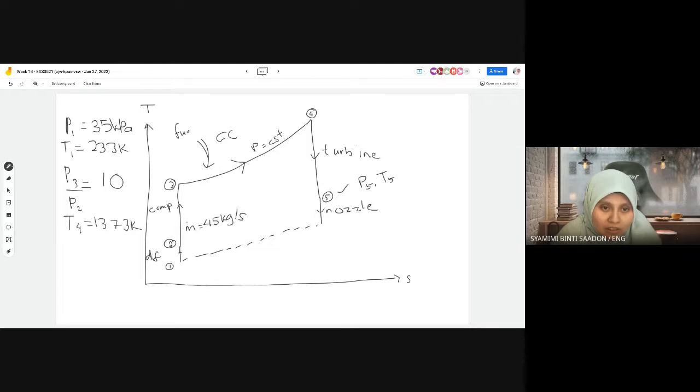At first only air. Air intake, right? 1 to 2 to 3, 2 to 3 only air. And then we add fuel. So the mass flow rate of the fluid in the core engine after entering the turbine will be M air plus M fuel, because we inject fuel here in the combustion chamber. Here only M air.